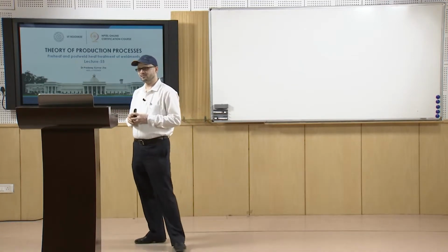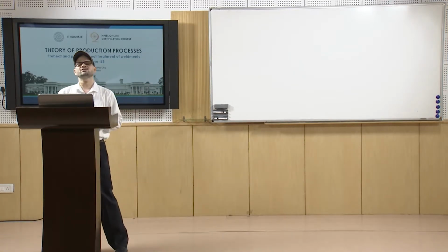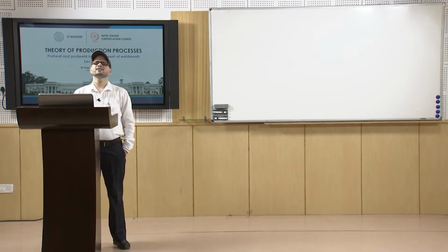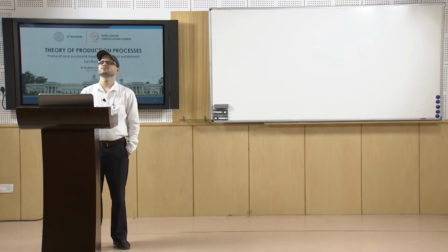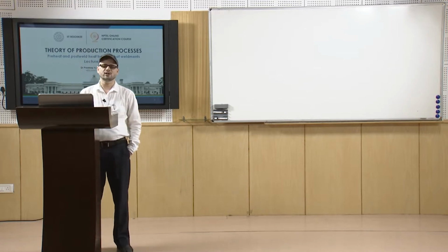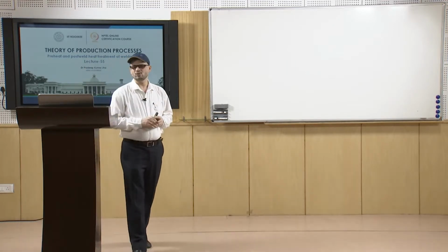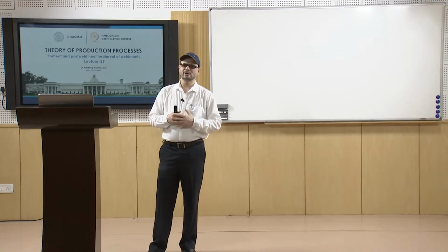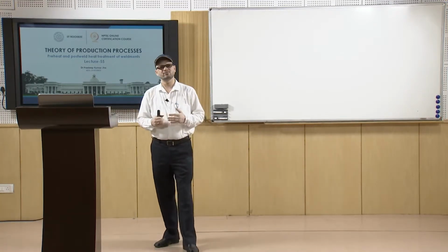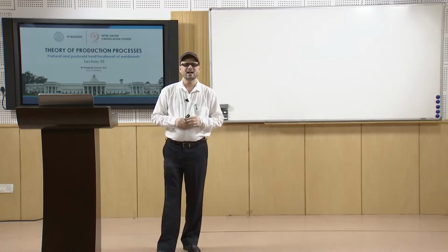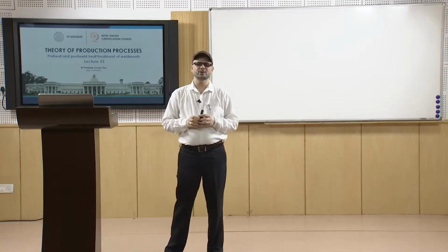Then you have quartz lamp heating, which has the advantages of fast response time, efficiency, cleanliness and fast cooling down. The disadvantages are high initial cost, fragility and sensitivity to contamination.